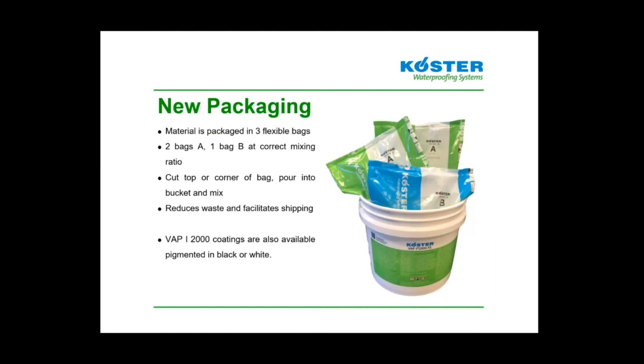Recently, we've updated the packaging of these products. Material is now packaged in one plastic bucket with 3 flexible bags. It contains 2 bags of the A component, the resin, and 1 bag of B, or the hardener, already packaged at the correct mixing ratio. You cut the top or the corner of the bag, pour the components into the bucket, and mix. So you'd pour both A components into the bucket, and then add the B component, mix for your standard 2 minutes, and then the material will be ready to install. This facilitates shipping and reduces waste.